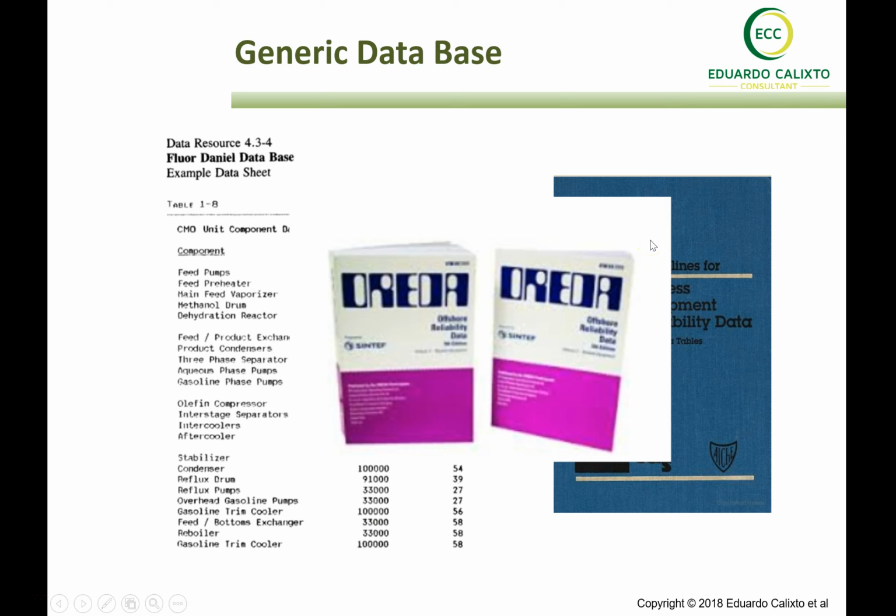What is the concern regarding OREDA specifically? The main concern is that most of these databases were built based on offshore platforms in the North Sea, in the UK, and such equipment has specific environments that are different from other regions of the globe.